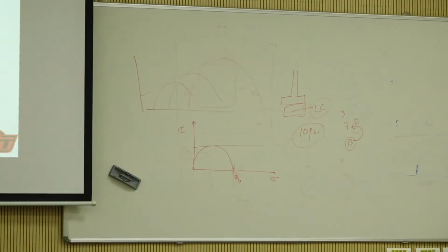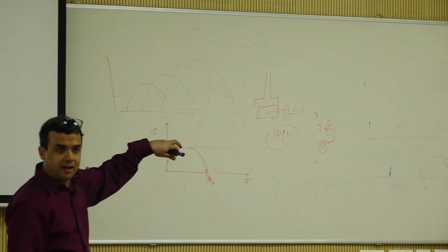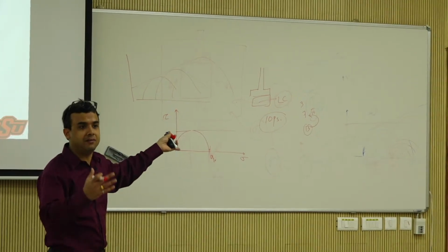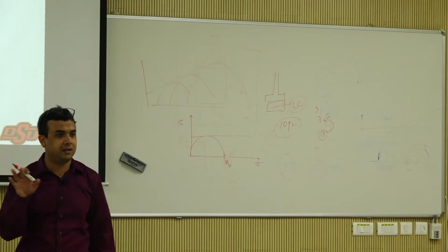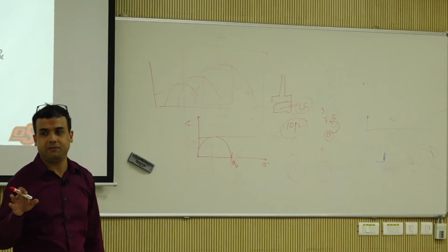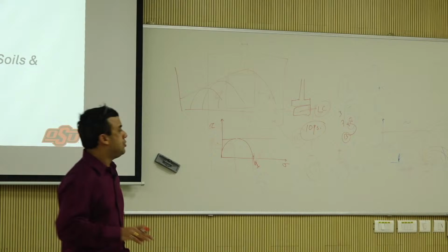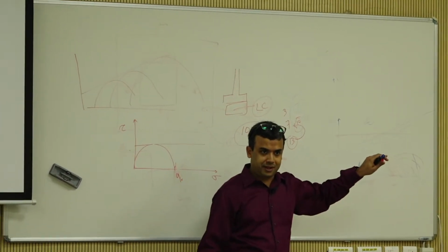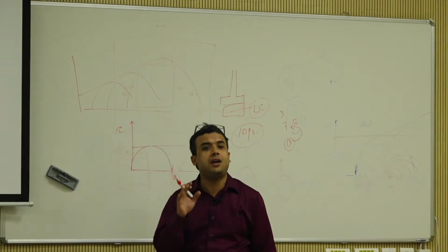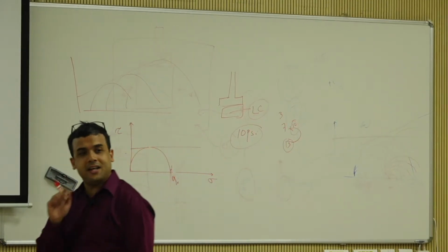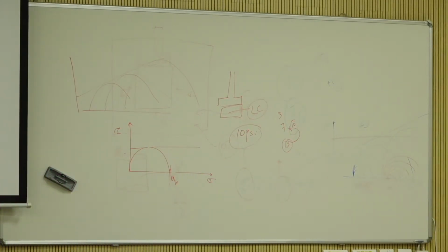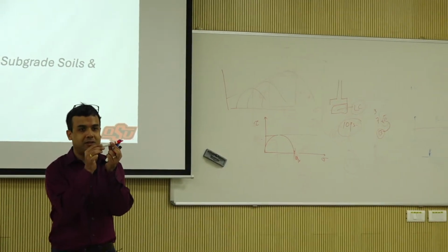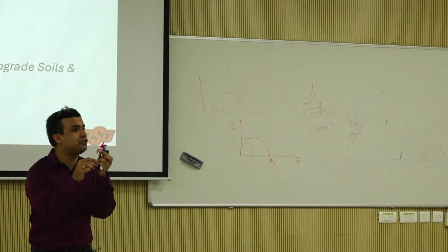So that's called feedback. Okay, and the thing that governs that is something called PID, proportional, integral, and derivative gain. We are not going to go into that. That's equipment stuff, design stuff, right? So a stress controlled test in the real world honestly does not exist, because a machine only has control over what? The deformation. Machine does not control the force.